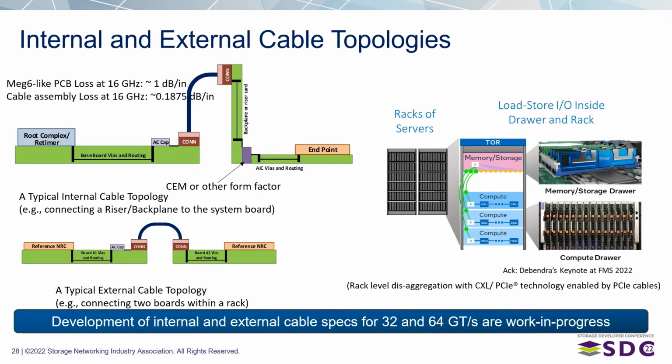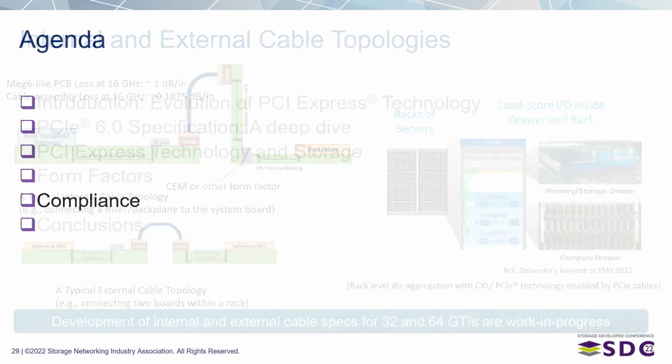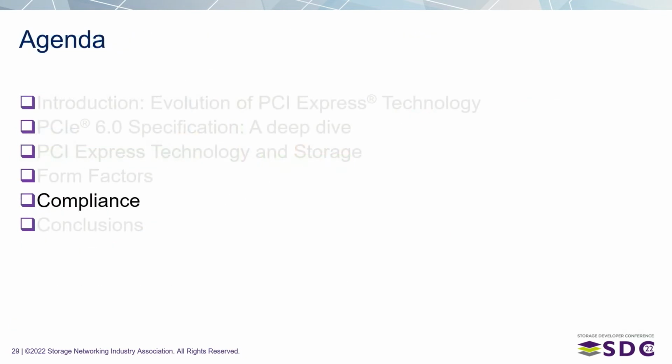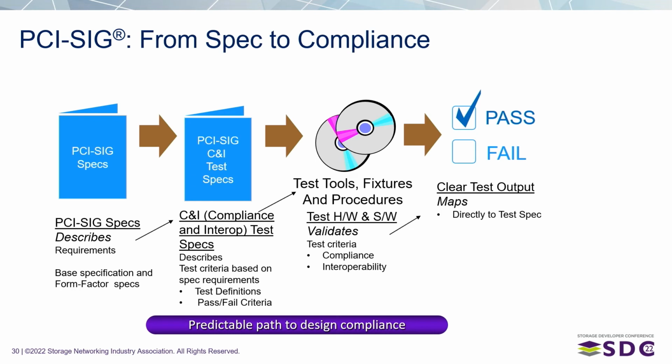And there are other things that we are working on, like unordered IO, which is basically going to fundamentally change things. PCI Express, like CXL and these other load store topologies, are moving towards more of a fabric kind of thing. It's a gradual shift, but it's a very strategic shift that's happening, right? So something to keep an eye out for. Clearly the normal mode of load store and the frequency doubling continues, but in addition to that, we are having those.